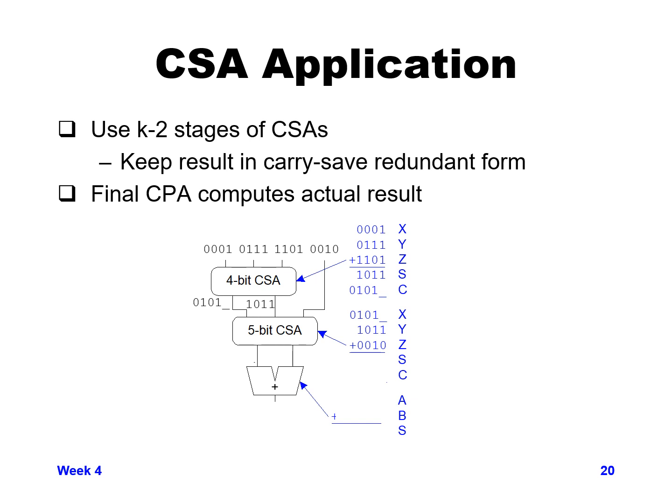And so then we can send that into a final sum stage, a normal adder, instead of these CSA functions, and add the carry and the sum together in a 6-bit adder and get a result out. So the final normal adder produces our sum coming out, which could conceivably be up to 6 bits, depending on the values of all of the different inputs. So this is a way to get a function of a 4-input adder that produces a lot less delay than using 3 sequential adders.